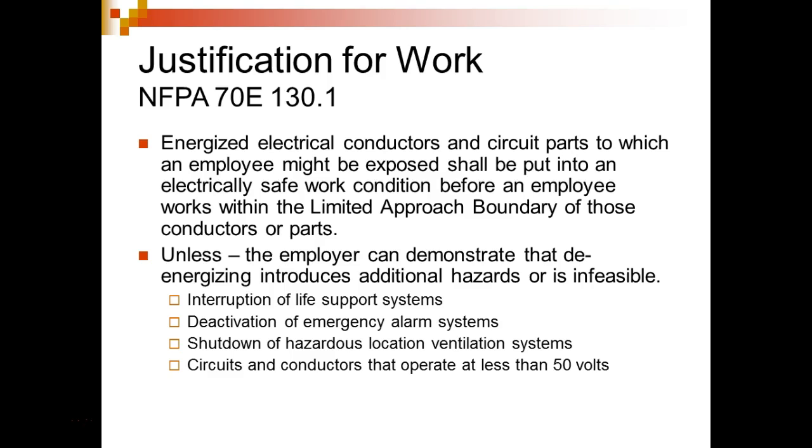Now, how do they blow the meter? Well, DC is about that too. We have problems when they're learning how to measure current and learning how to measure voltage. So they'll measure current, and then they forget to set up their meter to measure what? Voltage. And they'll leave it on current. Now on voltage, people don't understand this, but our meter has an extremely high resistance. Most meters, this meter right here, is over 10 megohms when we have it on voltage.